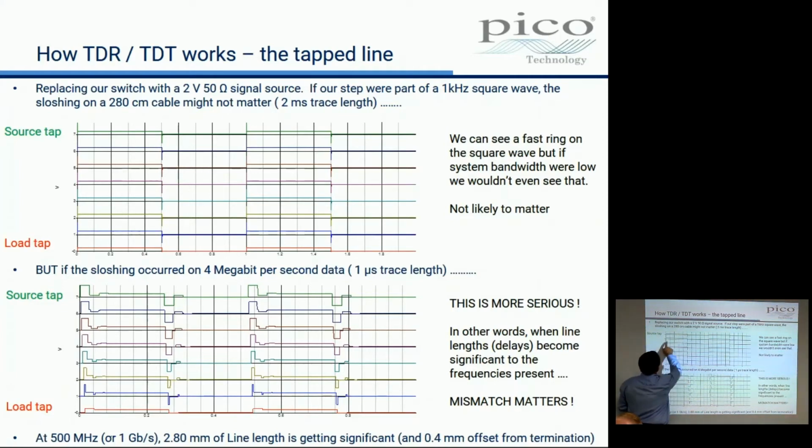But you can see I've got a kilohertz going in, I've got quite a clean waveform coming out, but all the way along the line I've got these high frequency spikes. Now the fact is that things with kilohertz waveforms in probably don't have the bandwidth to see those or care about those spikes.